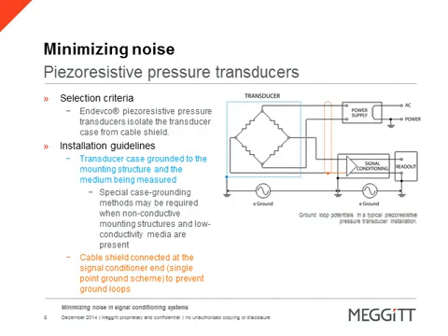If you see the diagram to the right, you notice that the blue area around the bridge itself is considered the shield of the accelerometer. It is not connected to the return of the signal going to the amplifier. That is shown in the red circle, is the actual shield of the cable. So it's not connected, and that is providing the correct grounding technique for our pressure transducers.